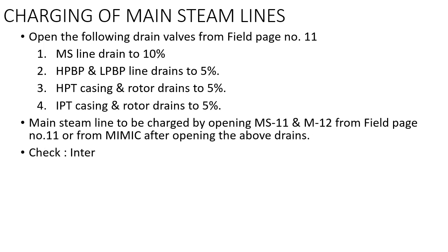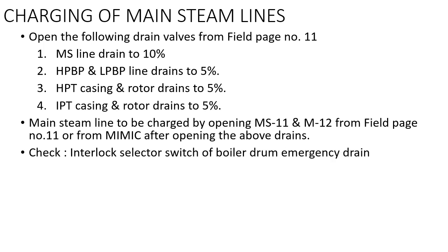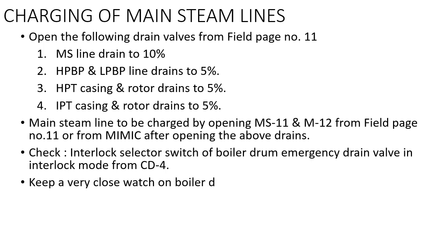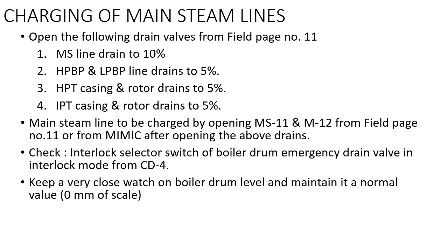Now this charging can be done after some vacuum is produced in the condenser. So we can do that afterwards, after taking the ejectors in service. Before going for this, you must check the interlock